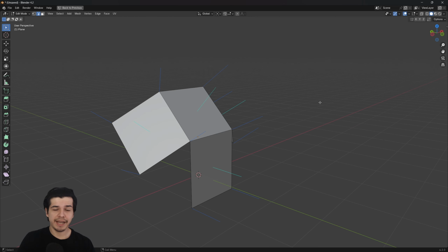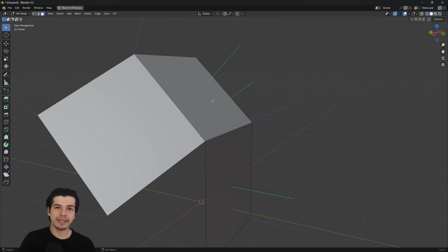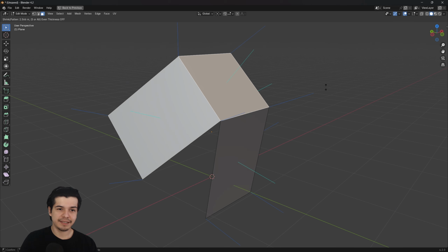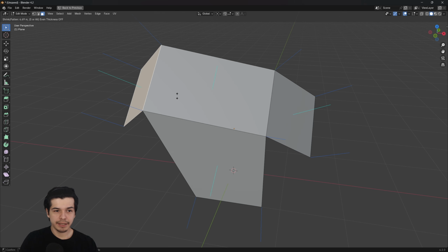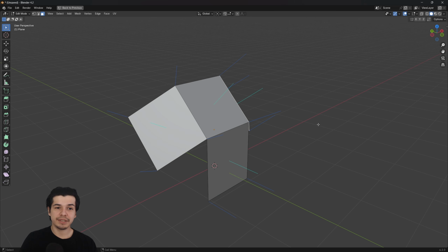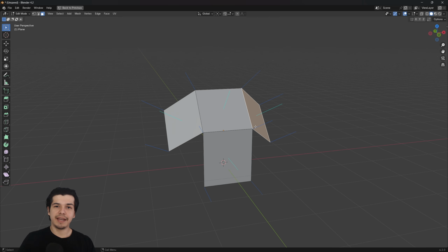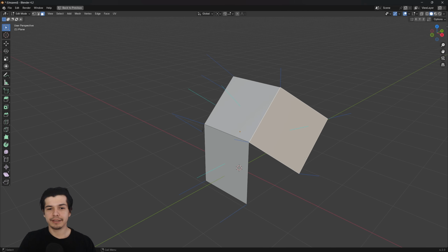And now the direction. When we did the scale along normals, as you can see, we have basically what this function does. It's following this scale. It's following this face orientation. So if I go now Alt S, it does it along this. The same here, Alt S does it along this. And here and here. Whereas if you just scale, it's scaling it to all axes, and since this doesn't have the thickness, it results in it just changing the scale of these two directions the plane is constructed in. So it just does this.